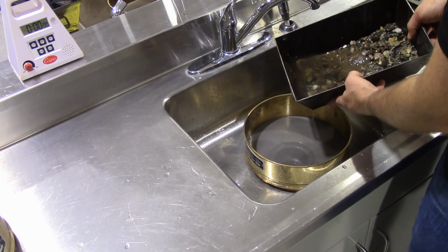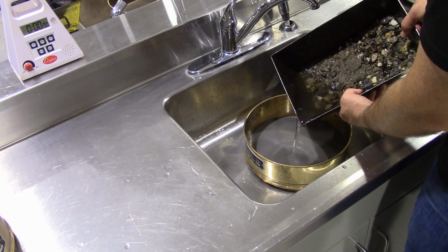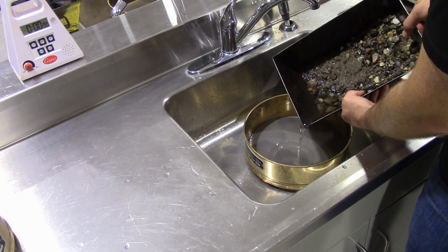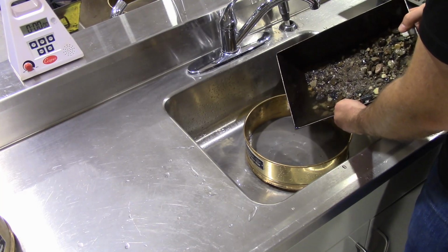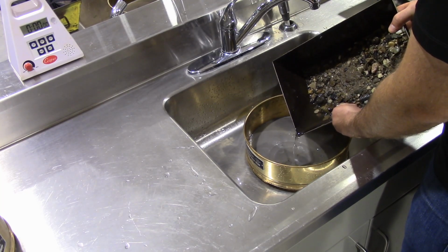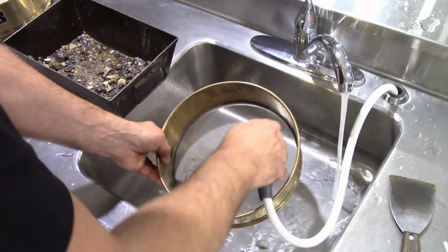If there is excess water in the pan, it will take much longer to dry the sample. To counter this, you may decant some excess water into the screens. Take care to avoid dumping any significant amount of aggregate during this final decant procedure. Shaking or tapping the sides of the pan will cause additional water to rise to the surface.